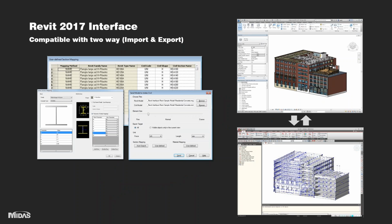For compatibility, in MIDAS Gen you can import from an AutoCAD DXF file, or if you have a STAAD profile or ETABS model file, you can import that model file to MIDAS directly. And for Tekla or Revit model files, you can import from the Revit 2017 version.